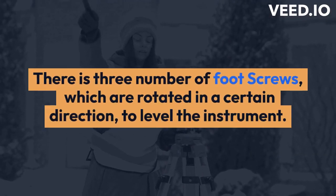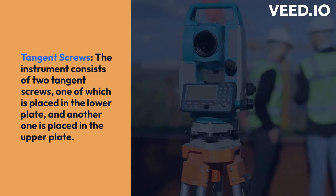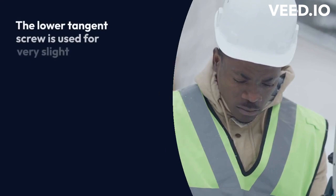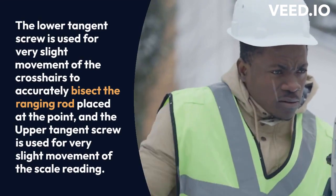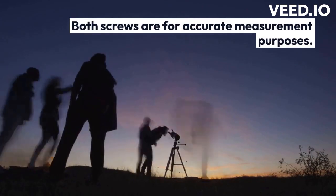Tangent screws. The instrument consists of 2 tangent screws, one of which is placed in the lower plate and another in the upper plate. The lower tangent screw is used for very slight movement of the crosshairs to accurately bisect the ranging rod placed at the point, and the upper tangent screw is used for very slight movement of the scale reading. Both screws are for accurate measurement purposes.